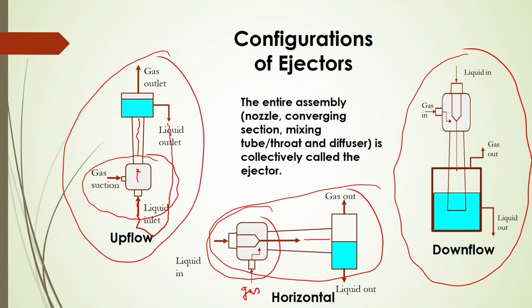In this way you can get more residence time of the gas inside the column, where for slow reactions it is sometimes recommended to have more residence time, or longer time, to get more mass transfer.